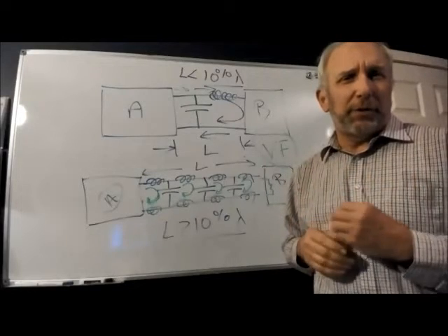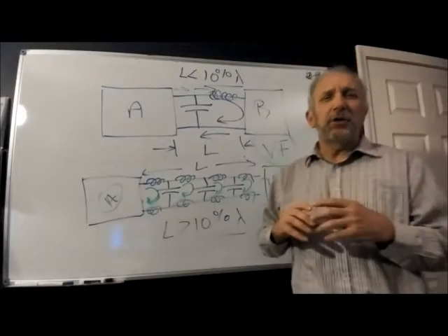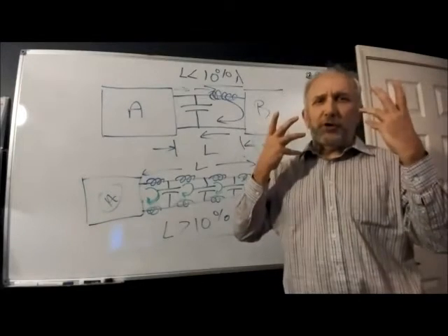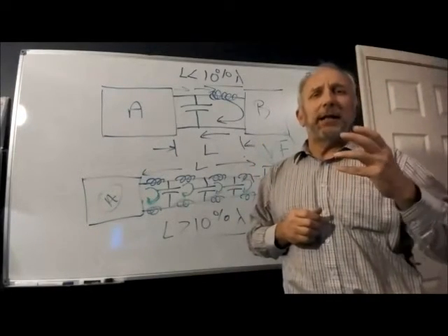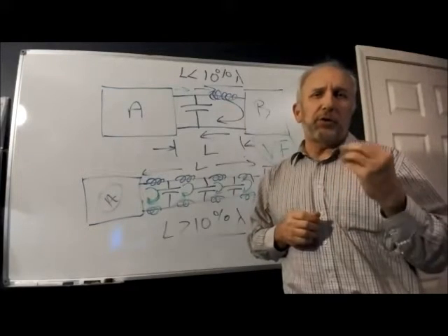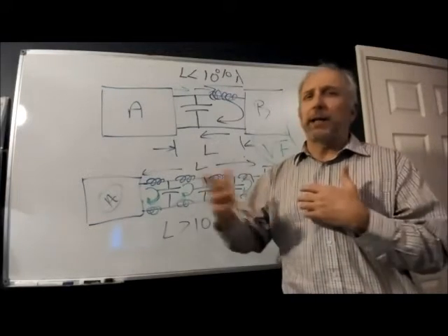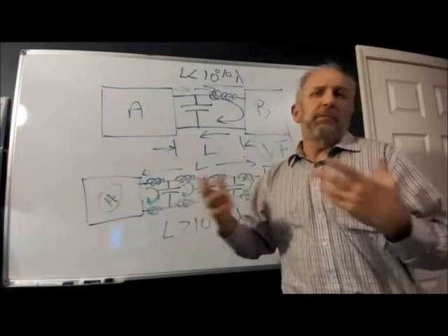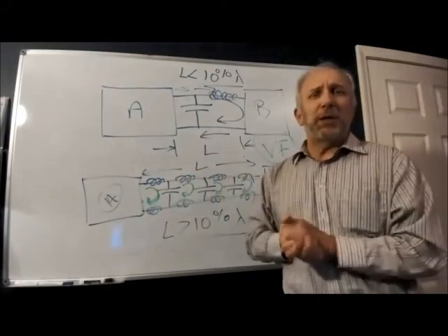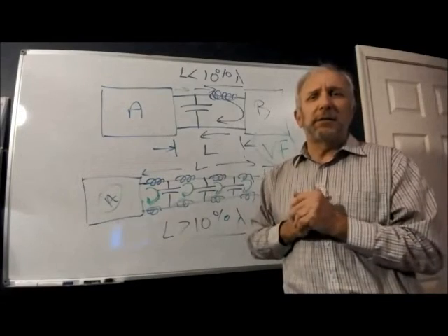All I know is we have some distributed inductance. What I generally do, just from a symmetry standpoint, is allocate the loop inductance into segments of partial inductance, and I allocate that across both the source and the return line. Does it matter? I don't know. Maybe someone else can comment on that.